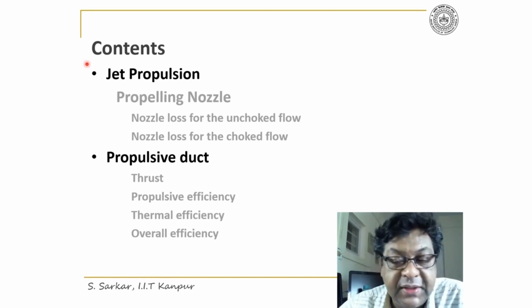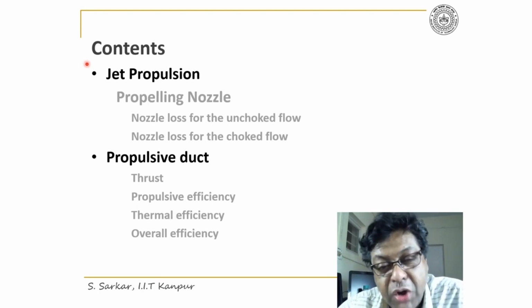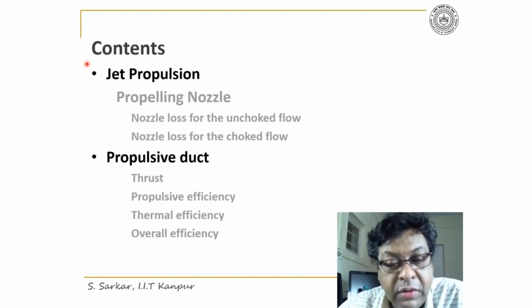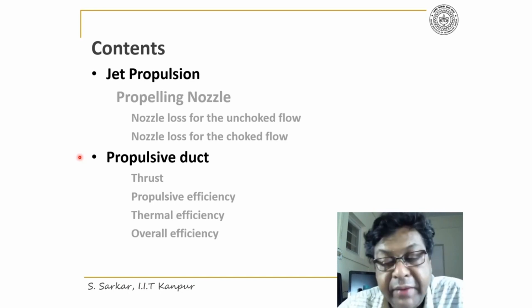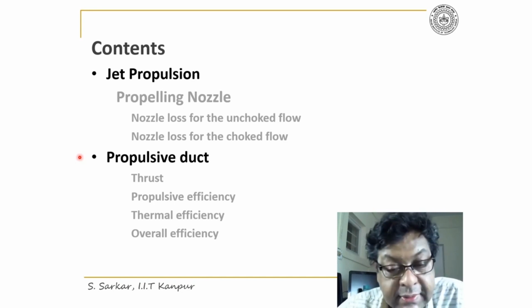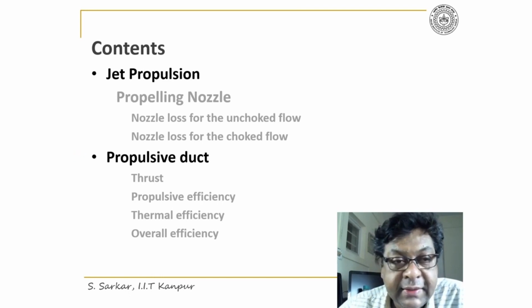Under jet propulsion, I'll discuss today the propelling nozzle, the nozzle loss for the unchoked flow and for the choked condition, and then the propulsive ducts. I'll derive the expression for thrust, propulsive efficiency, thermal efficiency, and the overall efficiency.